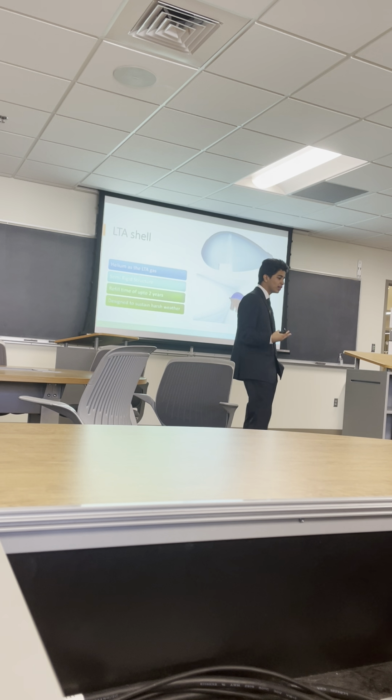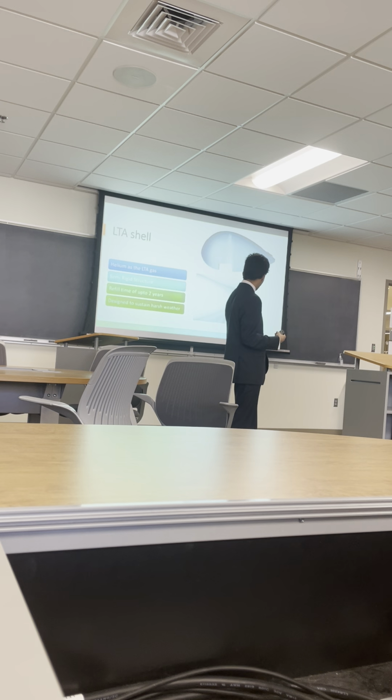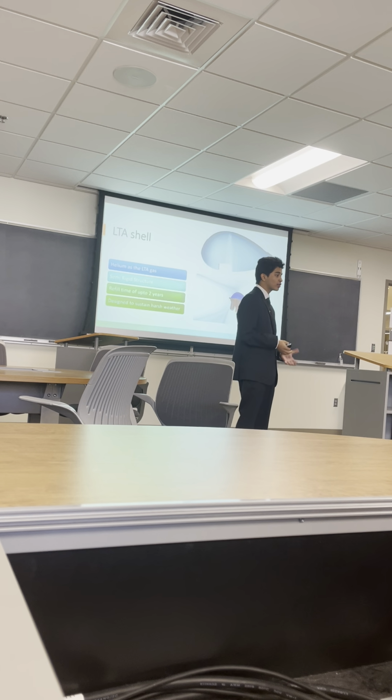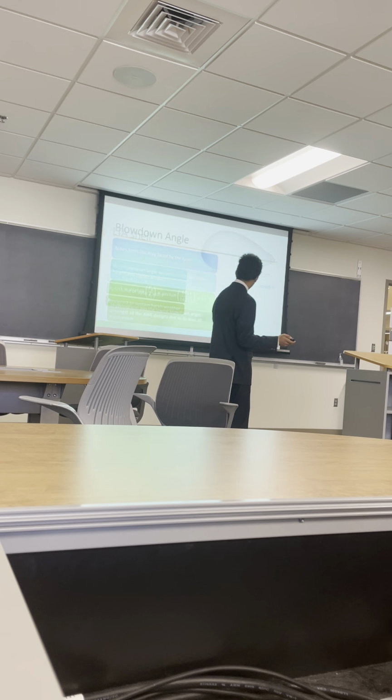It comprises 3 layers: a polyvinyl fluoride that acts as an environmental barrier, a polyethylene layer that acts as a physical barrier, and then a urethane layer which acts as a heat barrier. This semi-rigid structure is designed in such a way that when it goes airborne and then comes back, the pressure inside changes in such a way that the lift stays constant, and it can be used for up to 2 years without needing a helium refill, which is quite significant.